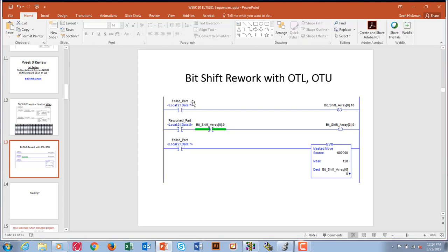And then we advanced, the array keeps advancing. But when that 0 went down the line, when that 0 got to 8, we said, hey, there's an opening on the line. We want to put the part back on. So we push this button right here, and we are able to put a part back in the line. Then the line would have all 1s in it. Hopefully we're making all good parts, 1, 1, 1s. But if we had a bad part, we put a 0 in there to indicate that we didn't have it, and then we pushed a 1 back in.